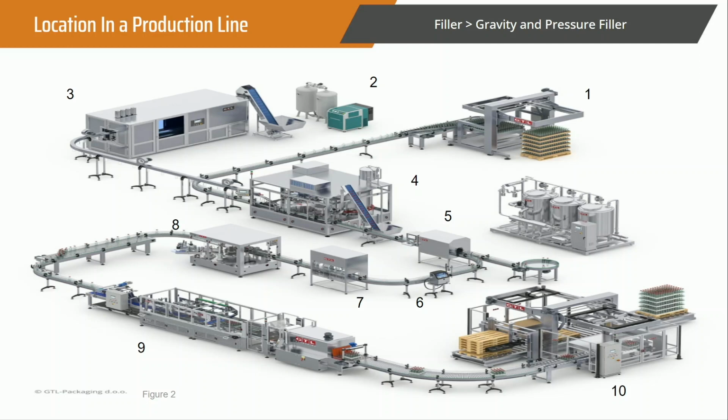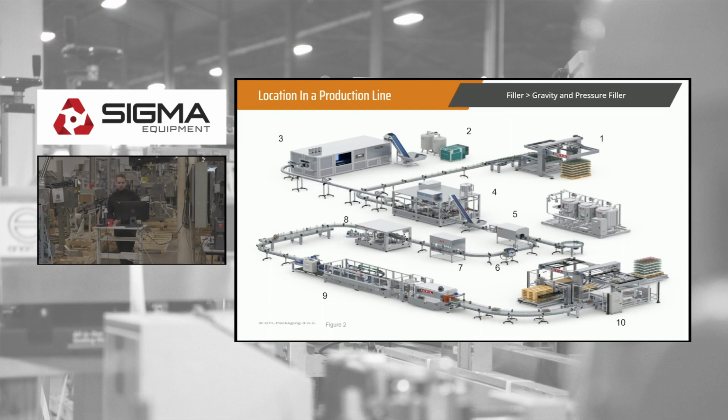Moving on into figure 5 there, that's going to be some form of product inspection. A lot of times you're looking at fill level inspection to make sure the bottles are filled uniformly. Moving on, if it fails inspection, it's going to move over to an accumulation table. But if it passes, we're going to be coating it, sterilizing it, down to figure 8 is going to be labeling. Number 9 in this case is going to be a shrink bundler variety, and then you've got over to palletizing. So again, you're not going to see both a depalletizer and a PET blower in a lot of facilities because they're usually doing one or the other, either bringing in their own bottles or making their own.